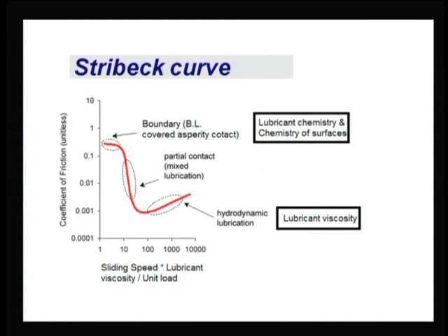Boundary lubrication mechanism basically is a solid lubrication. A solid form of the lubricant remains intact with the surface. If it is a one molecular thick liquid layer, then it will act as a solid, and it can be called a solid lubricant, it can be called boundary lubrication.